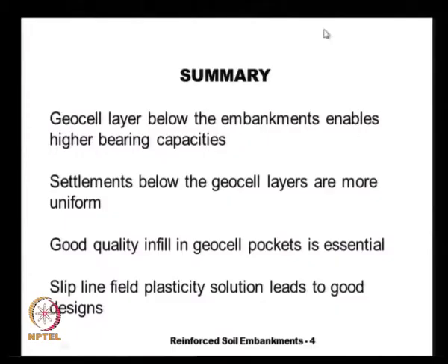If we form a normal slip circle, the bearing capacity factor is about 5, but in this case, because of the provision of a very stiff Geocell layer, and the action being similar to the squeezing of clay between two stiff and rough rigid platens, the principal stress field itself gets rotated,